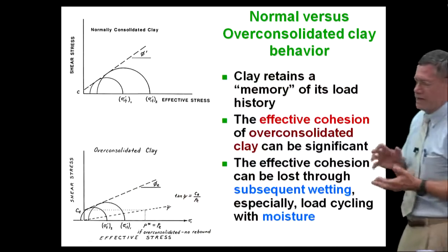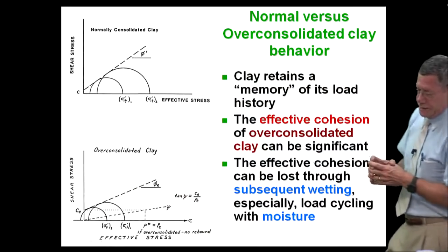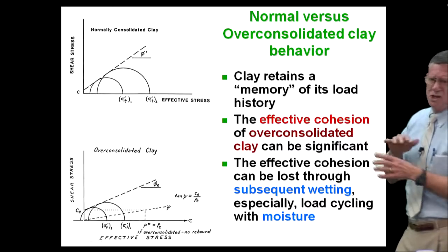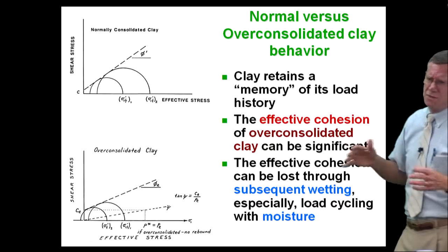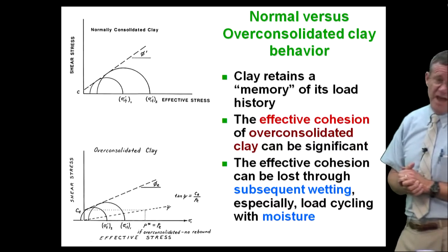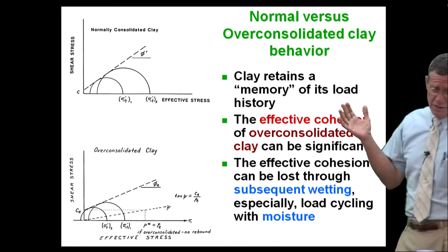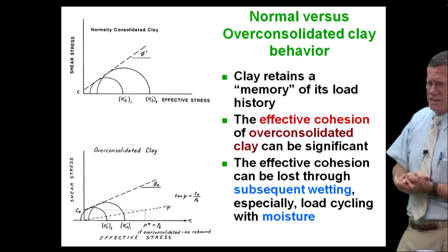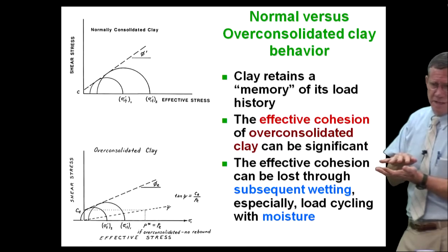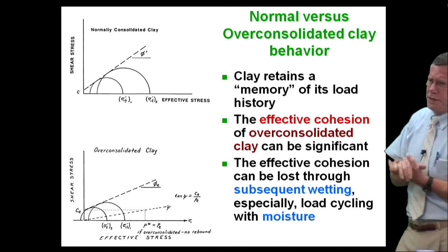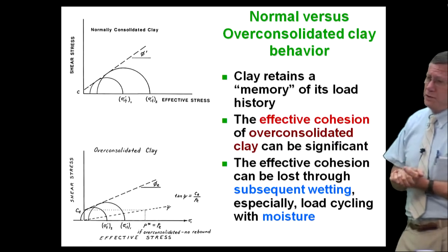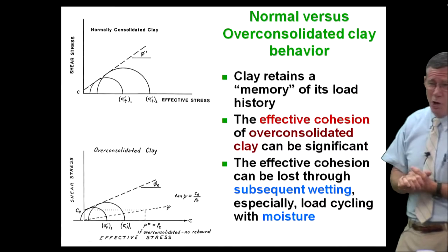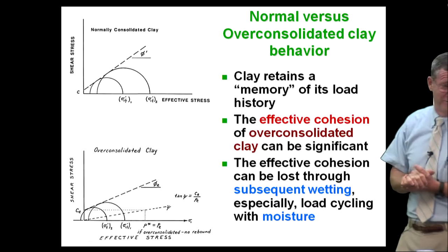So if we actually take a direct shear test, we look at ASTM D3080, standard, cheap direct shear test, you can shear the specimen at 0.05 inches per minute. That is fast in the world of clay. I'm talking permeabilities 10 to the minus 6 and lower. That's really fast. If you took that same specimen and instead of shearing it over a period of 30 minutes, you did it over a period of 30 days, which is like it is in the real world, in the field,